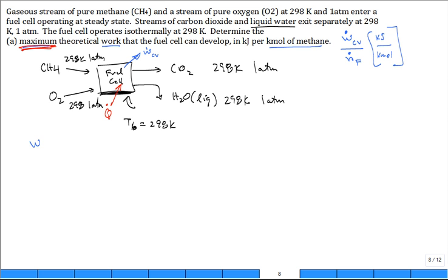And so what we have to do is go slowly and apply the first law. Once we have the first law of thermodynamics applied to this reacting system, then we can apply the second law to this reacting system. What's the equation for the first law look like? Q dot in minus W dot CV out. Just Q dot minus W dot CV. Okay.